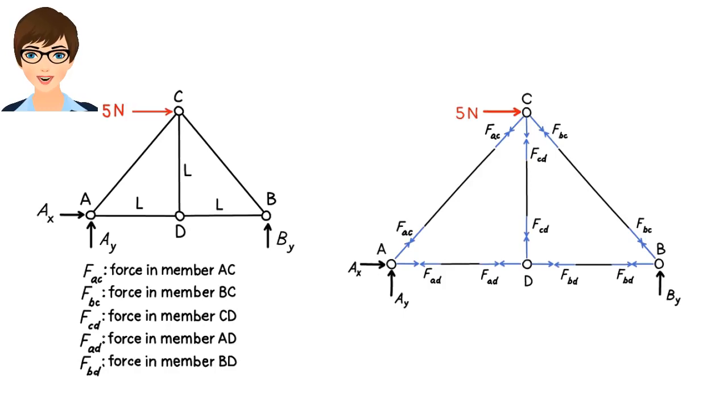Now we have the complete free body diagram for each member and joint. As I mentioned before, for the entire truss to be in equilibrium, each truss member must be in equilibrium, and each joint must be in equilibrium. We can easily see that the equilibrium equations are satisfied for each member. The 2 force vectors shown in each member cancel each other out, that is, their sum equals 0. And since there is no bending moment or shear force acting on the member, the moment equilibrium equation is automatically satisfied.